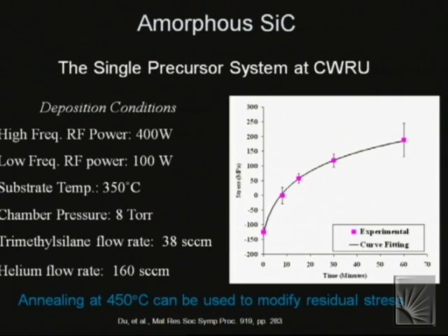The rationale being that copper needs to be isolated from the underlying transistor, which would require an excellent diffusion barrier material. And the thinking was that silicon carbide would be that. But not only does that film have to have excellent diffusion barrier characteristics, it has to have outstanding dielectric characteristics, and I think the verdict is still out there. I haven't really kept up with that line of research, but I knew that there was a large body of research out there that could guide us in developing suitable deposition processes, so we went ahead and did it. We did note that no one had at this point used that precursor to fabricate MEMS devices, so that was an additional motivation. So of course we're going to track stress as a function of annealing temperature.